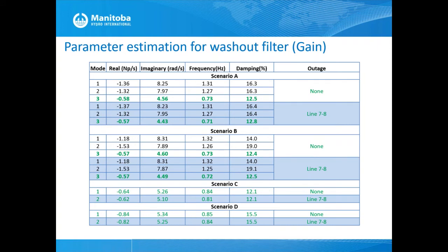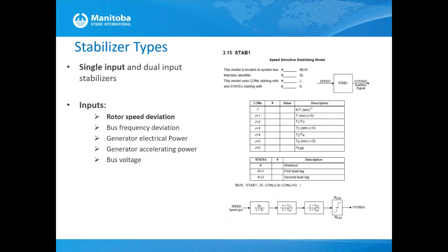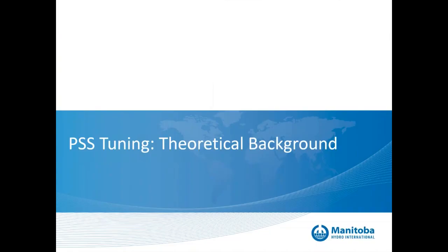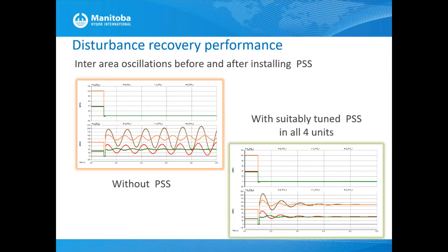I think we have a couple of questions. Question number 1, I think, is about how we define damping percentage. Damping percentage can be defined as the ratio between 2 successive oscillations. So if we take a plot here, let's go to an unstable situation. If I take these successive peaks, let's say these 2.